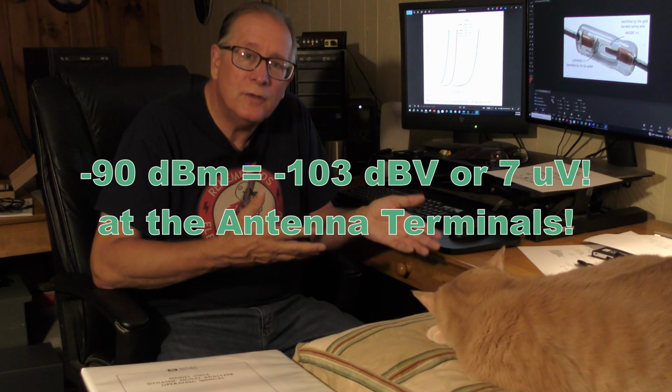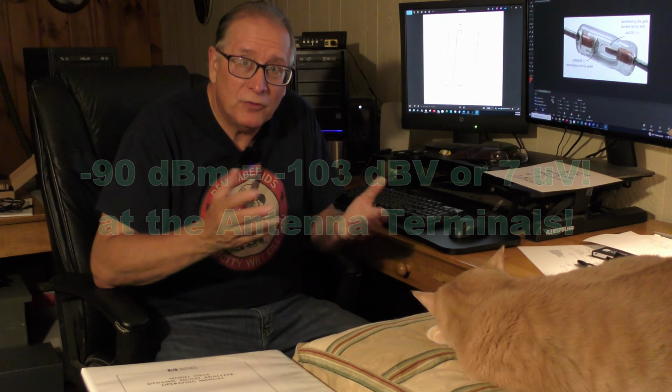What's the distortion doing? The distortion is not doing much. You've got low signals. Some of these crystal radios are capable of signals as low as -60, -70, -80, -90 dBm. Some of your ham receivers can't even detect -90 dBm. So some of these crystal radios are pretty hot. And when you're down in that range, you certainly aren't doing old-fashioned peak detection. You're not turning the diode on enough to actually prove out half-wave rectification in a meaningful way. Something else is happening down there, and it's called mixing or product detection.